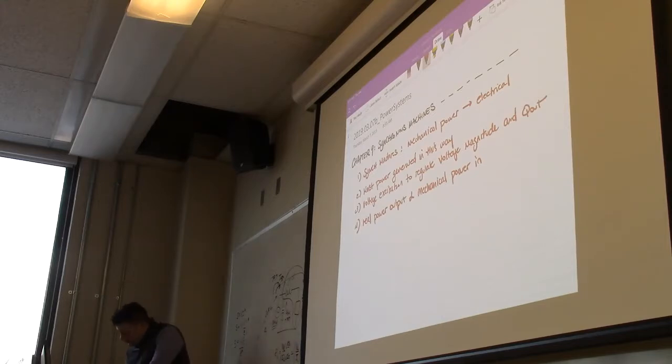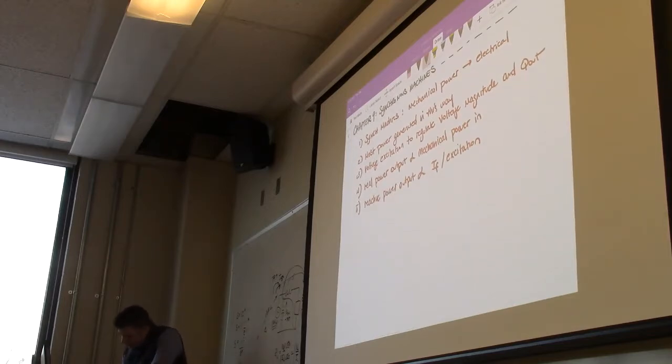The reactive power, which I said a second ago, is going to be related to a value which is I_F, and this is the current along the field windings. And that's the same thing as saying we control the excitation of the rotor. And so a lot of this stuff, some of these terms don't really mean anything at the moment. It's a little bit of an intro, and as we get into the chapter, a lot of these terms, especially voltage excitation, will start making more sense.